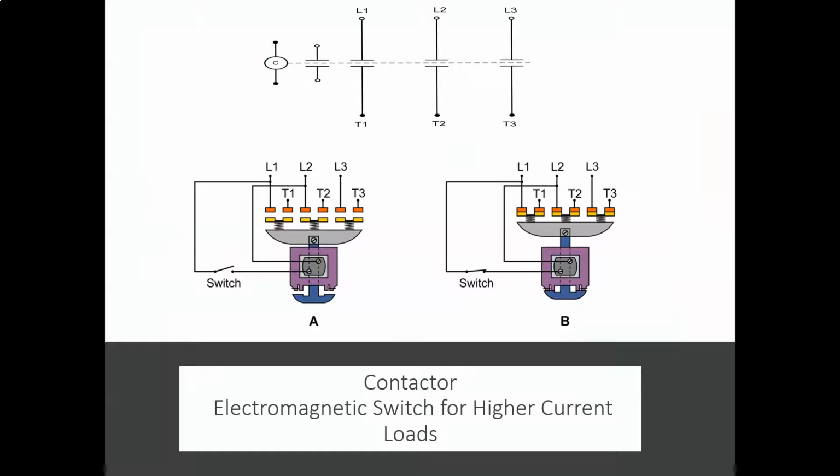All right, then we have contactors. Relays and contactors are, in general, the same thing, but contactors are for switching much higher currents, right? When you get much higher currents, you have a problem with arcing, which is going to damage your contacts, and you need materials large enough to handle the higher amount of current. So that's why contactors are just physically bigger relays.